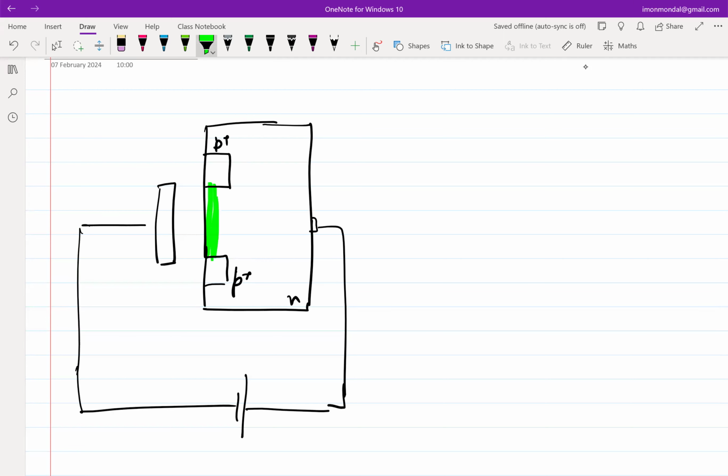We want the carrier transport, in other words the whole transport, to happen within that shaded region. We don't want the holes to escape through a forward-biased PN junction, which essentially means that we have to ensure the batteries that we apply are in such a way that they are all reverse biased, right? So let's take some example. Let's say this battery is 2 volts.